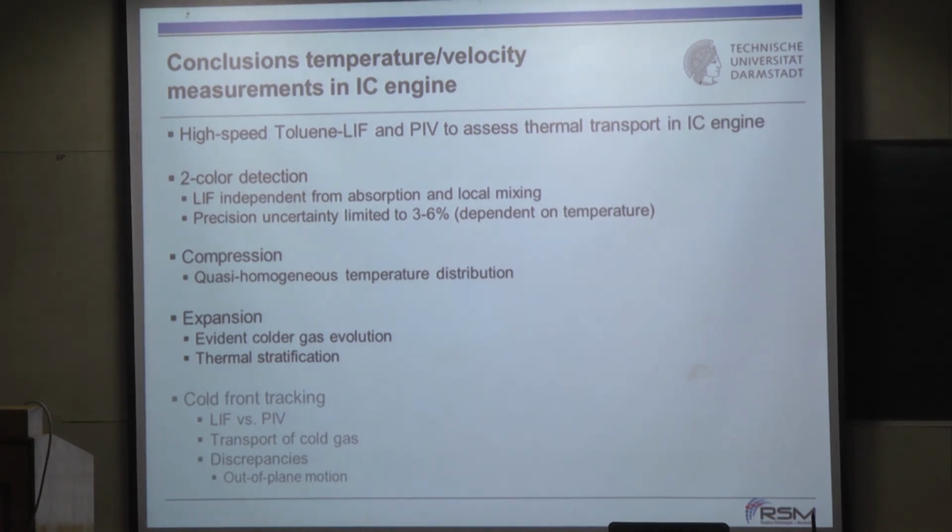So combining techniques, as shown in this example, can be very beneficial to have a better understanding of what's going on. And in principle, we now have a technique to measure thermal stratifications in different environments and not only in homogeneously compressed gases. When you have, for example, a spray going in, you can measure stratification due to evaporation cooling. I don't show that, but we have done that. It's in principle now possible with a limited precision. However, that can give some idea about hotspots and so on, and I think useful data for the future to be compared with numerical simulations.